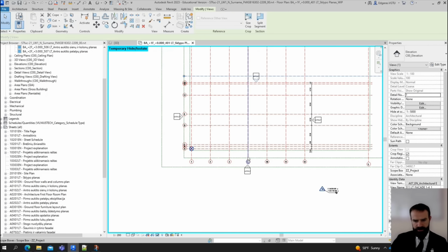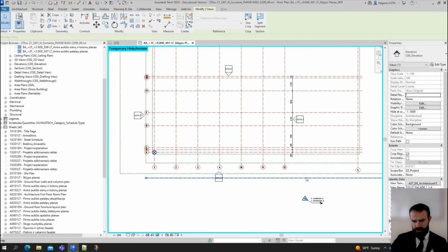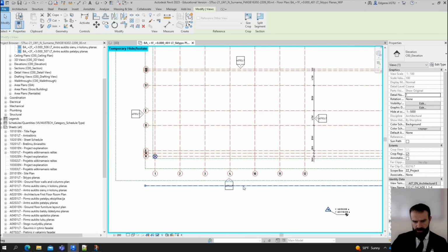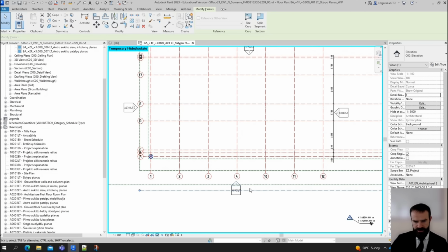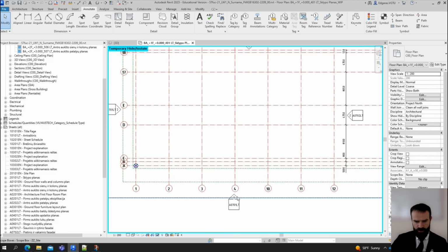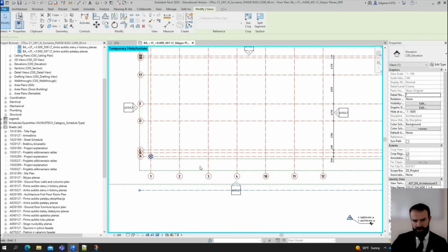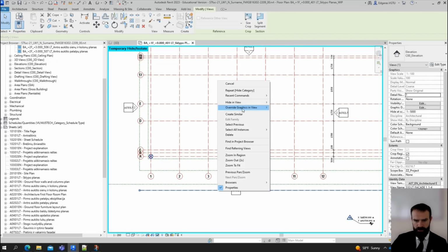And an important part is if I click on the triangle, this line represents the location of my section. So in this case, I would like to see this line inside this location, so it cuts and is inside the scope box. If it's not in the scope box, I will not see all the grid lines and other components, because if the object is not cutting the grid line or elevation, it will not be represented. So look what will happen.